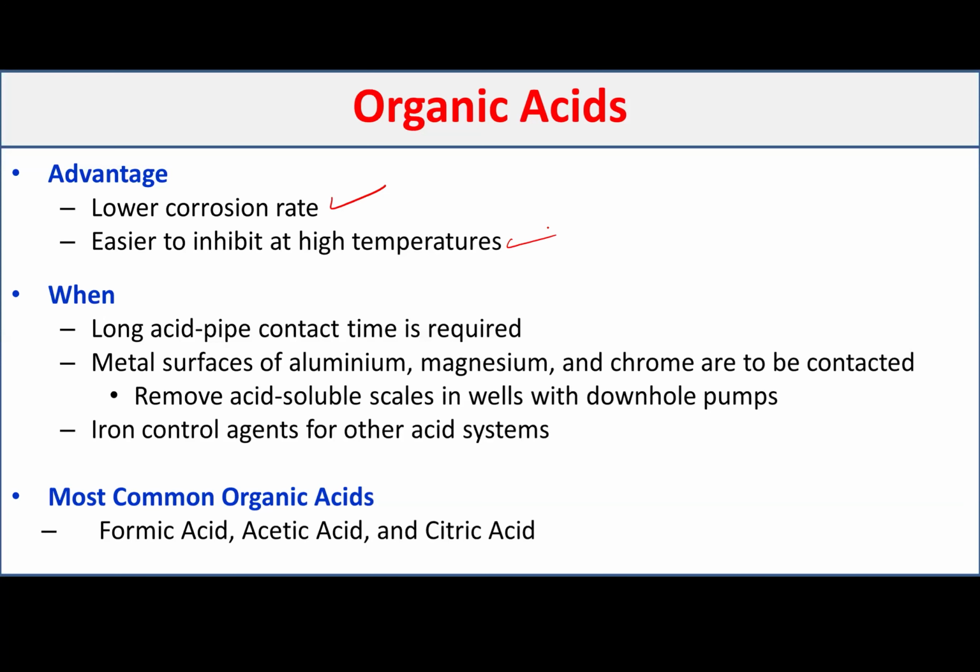If you have a really expensive, or what we call a low corrosion steel, that you are actually putting there with some sort of external layer to minimize the corrosion that's happening because of the produced water, because of the water during the injection or during production, or if you have an H2S environment or CO2 environment during the production phase, you are using a really expensive type of tubing system to minimize the corrosion that happens during the production.